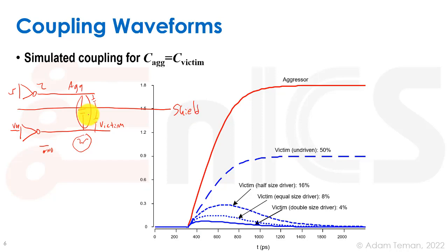And since our clock nets are really, really important, we're usually going to put a shield around them. If this is going to be a clock net over here, we're going to put shields on both sides of the clock net to protect it from any possible aggressors outside, so they won't cause any glitch. Our problem, as we're going to be seeing soon in an upcoming lecture about sequential elements, is